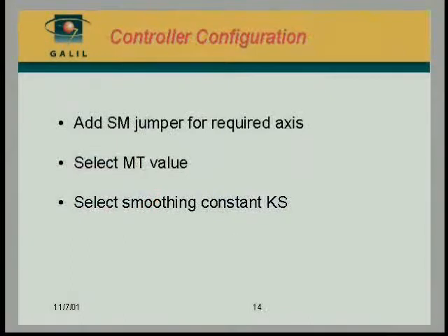Now, when it comes to the Galil controller, if you would like to use a Galil controller to drive a stepper motor, there are a couple of things we'd like to mention here. First, because Galil allows every axis to drive either servo or stepper, you need to notify the controller that you would like to drive a stepper with that particular axis, and you do that by putting a jumper. It's called the SM, and SM stands for step motor. You put a jumper at the right place for a particular axis to designate it as a stepper motor driver.